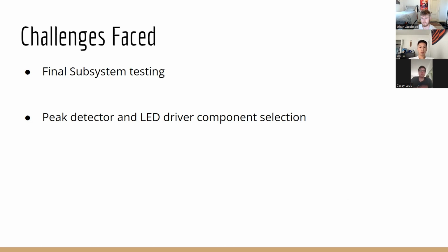What was happening is that if we were using a capacitor that was too small, then the gate voltage that was created for the MOSFET was too short of the threshold voltage, causing the light of the LED to flicker too much, even with constant frequency. By increasing the capacitance of our capacitor in the low pass filter, that smoothed out the current and signal better, and so kept the LED at a more stable brightness.